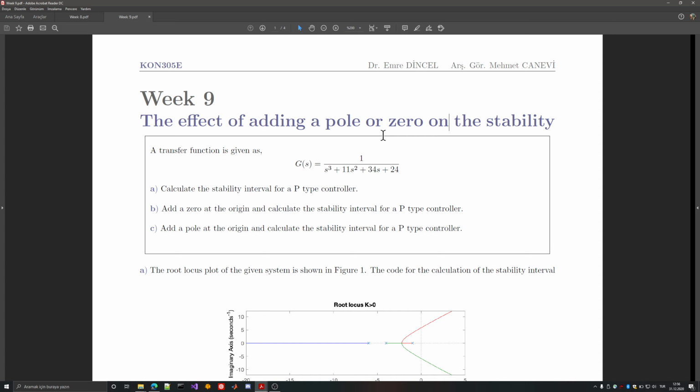So in the PI controller, think of this as you're adding one pole that narrows down the stability, but then you're compensating that with a zero so that your closed loop behavior is as you wish. And with the PID controller, you can even increase the stability even more, since you have 2 zeros.